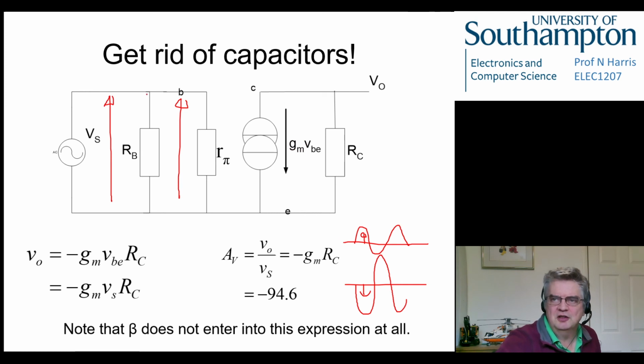This type of circuit is a superposition type analysis, or partial superposition type analysis, for an AC signal coming in with a dependent source, and it becomes very trivial to analyze this basic circuit to allow us to get an absolute value for the transfer characteristic of this amplifier under those operating conditions.